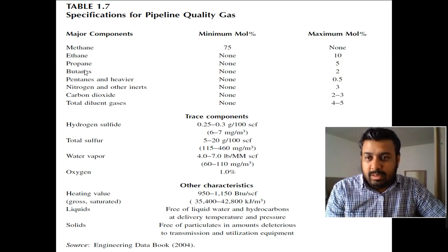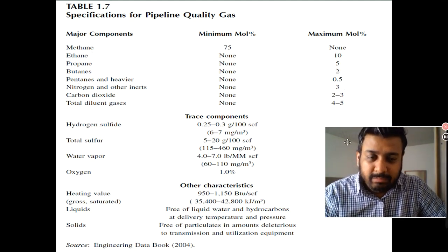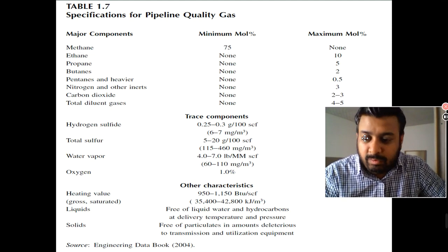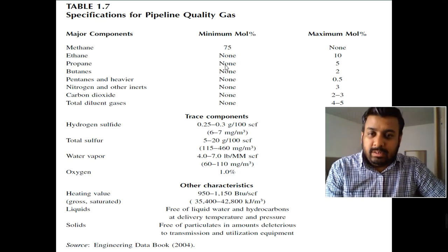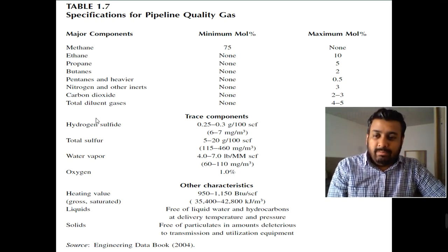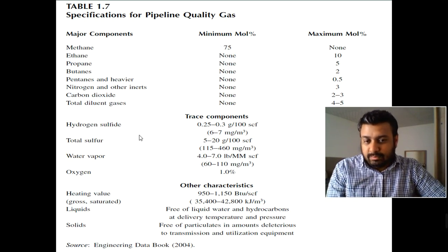And make sure that your major component is methane, at least 75% mole percent. As you know, you will sell this gas on the price of methane, so make sure that it does not have H2S sulfur, because it will reduce the price of the gas you are selling.